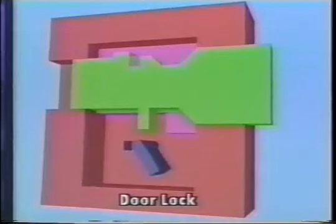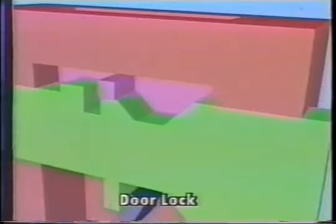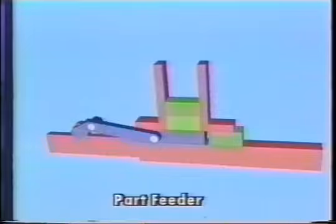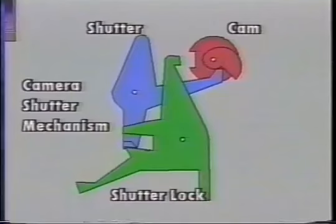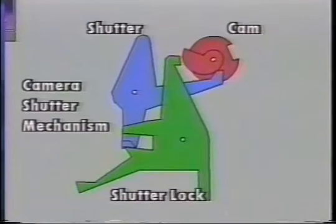Multiple contact mechanisms are more difficult to design than are mechanisms with fixed contacts, such as linkages and cams. The designer needs to identify which part features interact at each stage of the work cycle and to validate each interaction. Current computer-aided design programs provide little support for multiple contacts. The designer must perform many difficult computations by hand.